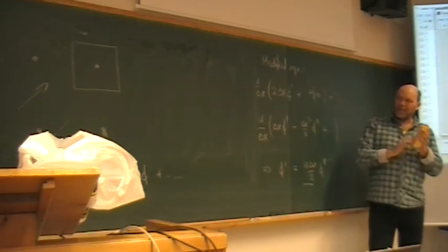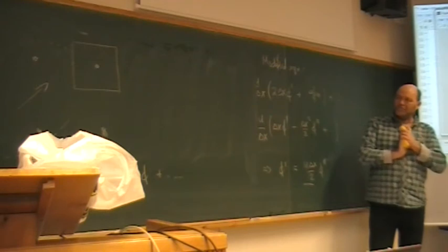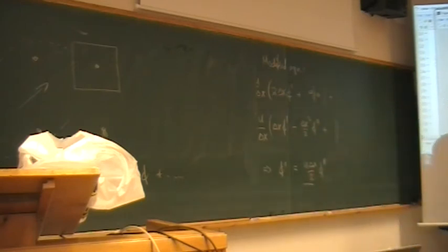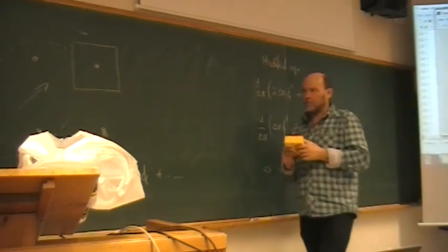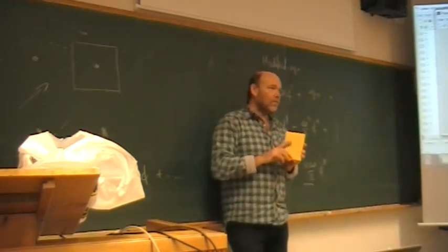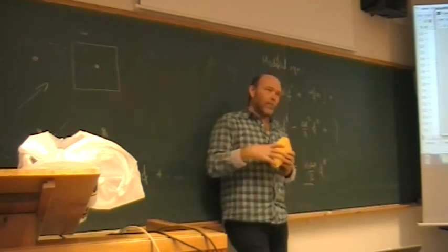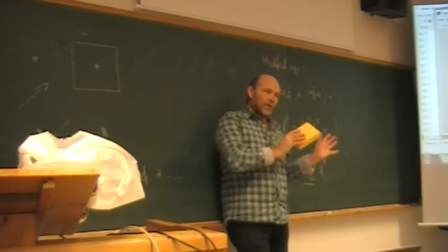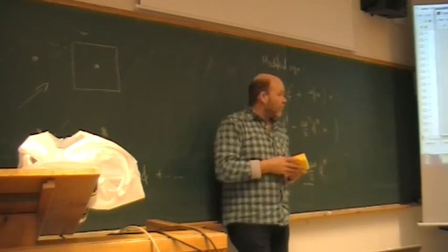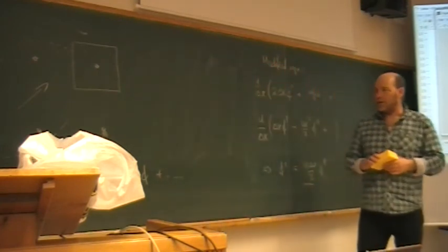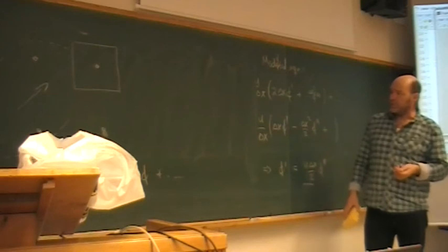So I don't think they really apply. You have these QUICK, quadratic upwind using 3 points, good enough, I would say. You also have MUSCL in several codes now, which is also a little bit more advanced, taking many more points on the upwind side, interpolating nicely, and performs reasonably well. So I won't pursue this theory any further.